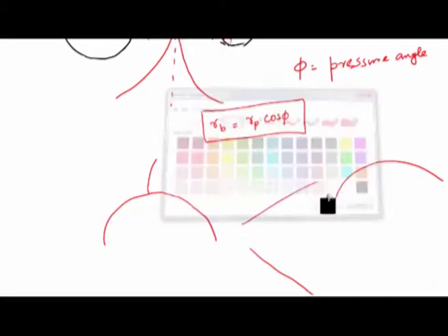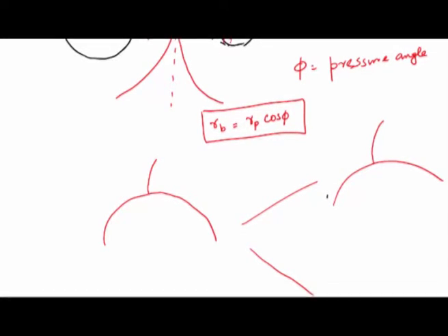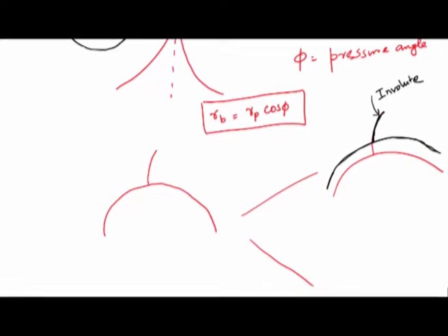So this is the gear tooth profile, and the dedendum circle is here. Therefore what I see in the physical construction is only this part. The red part is not seen in the physical construction, but this is a happy situation. I am at least sure that this part is involute, no issues, because the involute can be at any portion which is beyond the base circle.